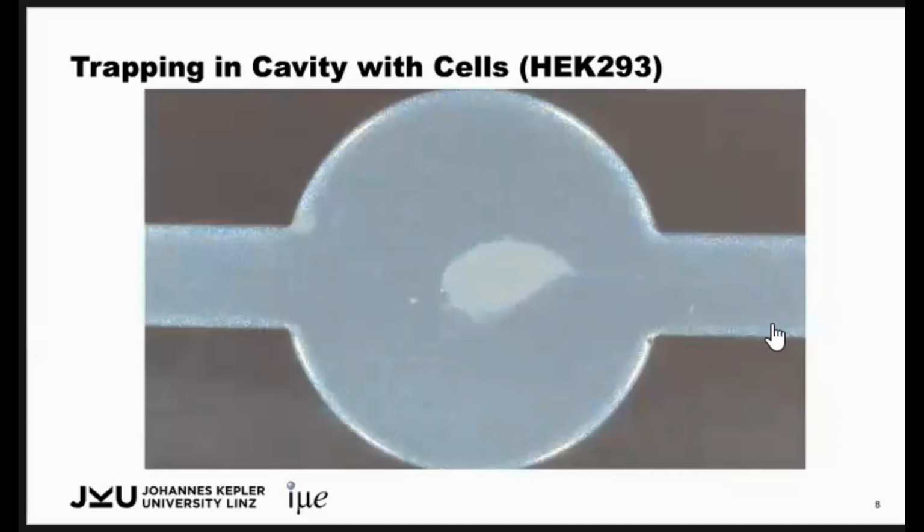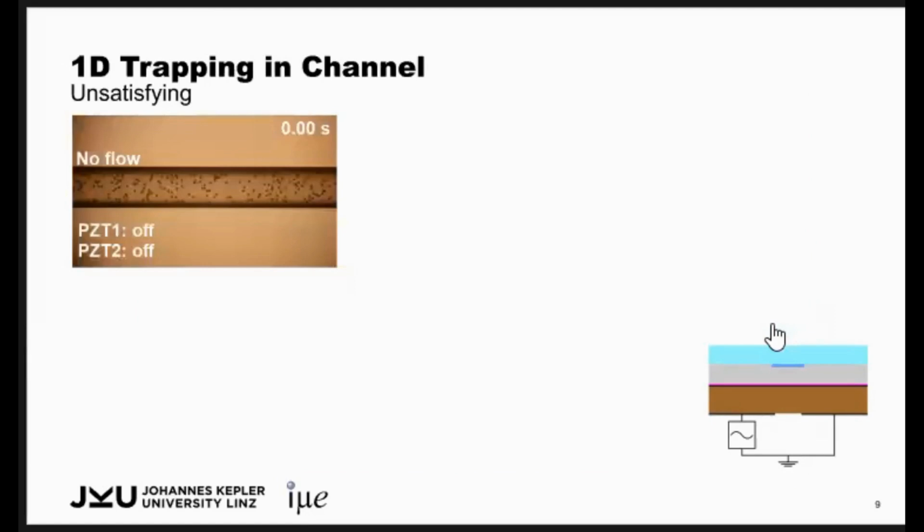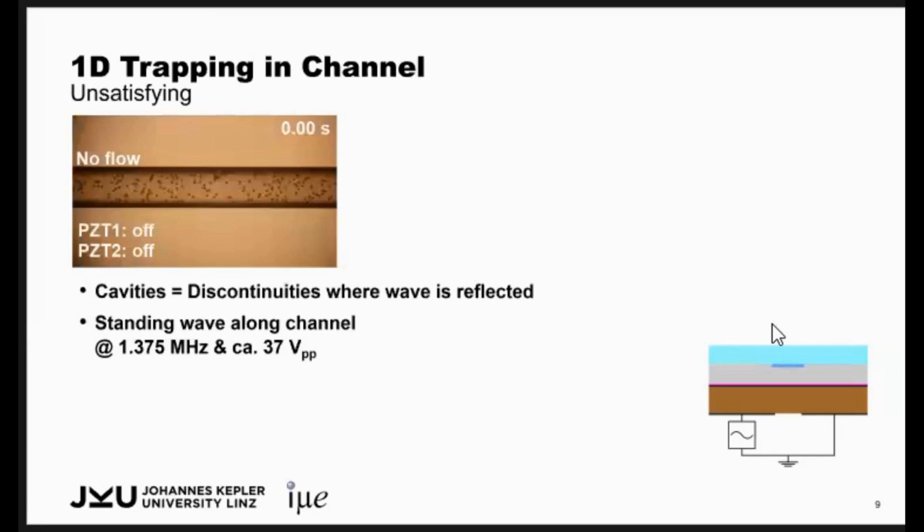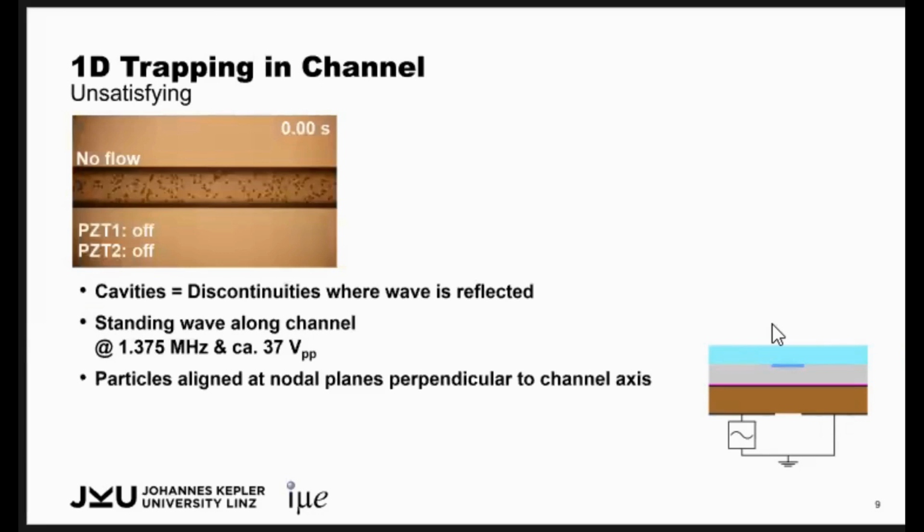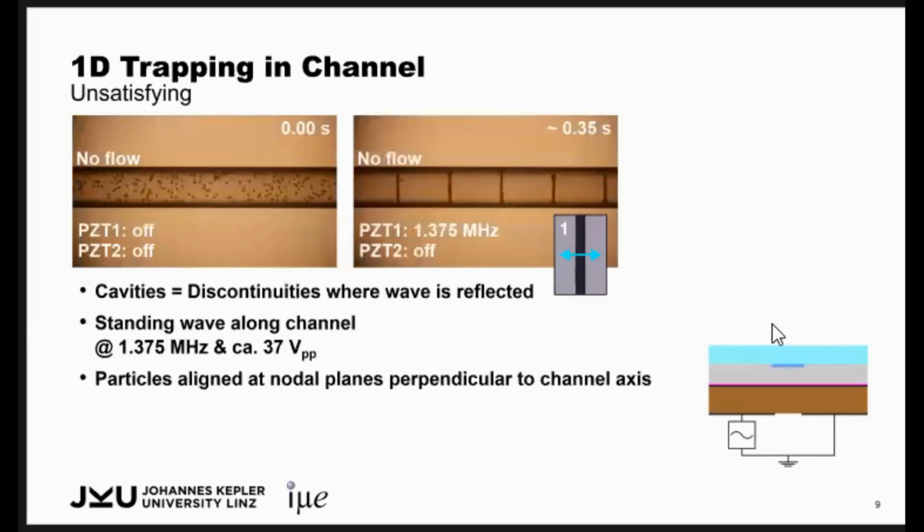So this was our trapping in the cavity, but we also found something else interesting in this device, namely we also found trapping inside the channel, because the discontinuity of the cavities between the channel sections is something like an acoustic reflector. So we can use it to generate the standing acoustic waves in the channel sections between the cavities. And then we have a standing wave with nodal planes along the channel, and there the particles will accumulate, and it looks like this. So then the question was, can we also trap particles with this?